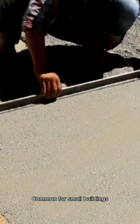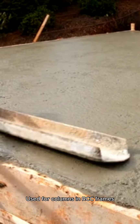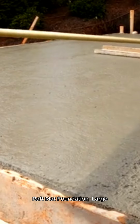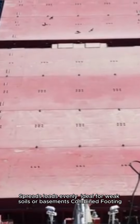Common for small buildings. Pad footing, or isolated footing: square or rectangular pads under individual columns, used for columns in RCC frames. Raft or mat foundation: a large concrete slab covering the entire footprint. Spreads loads evenly, ideal for weak soils or basements.